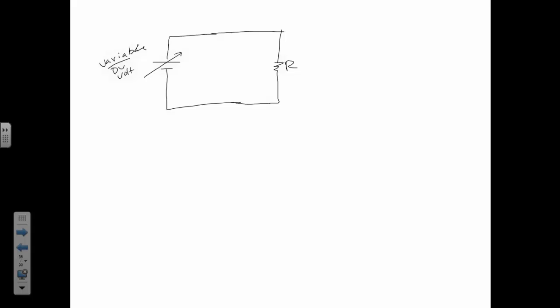I have 167 different values of this size resistor, of this physical shape right here. But they all have these little color-coded lines on them, and you can read those. There's a little chart here, and they use Roy G. Biv, the colors of the rainbow, to count out the numbers.